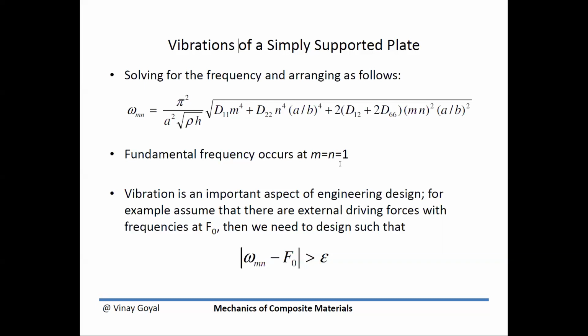So vibration is an important aspect of engineering design. Why? If you have a structure that has a natural vibration frequency, and the structure is subject to a loading environment with frequency content that could couple with the natural frequencies of the structure, then there's a potential that you could have a resonant condition.